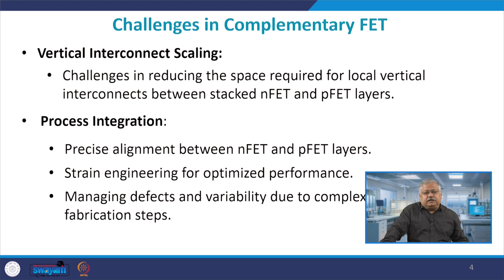When I say process integration, I mean to say between NFET and PFET. So, the first problem which comes when you do a sequential design is you need to place the NFET and PFET layer perfectly aligned over each other. If there is a small misalignment between the two, there will be a drop in the functionality of the complementary FET. So, precise alignment between NFET and PFET layers is an important requirement for characterizing the complementary FET.